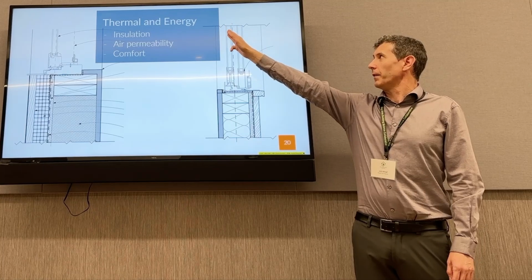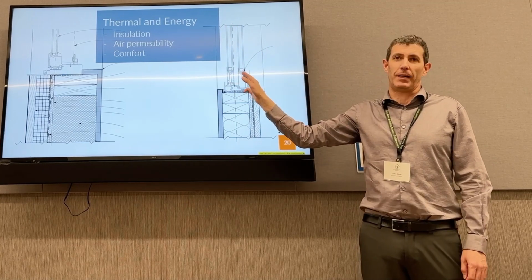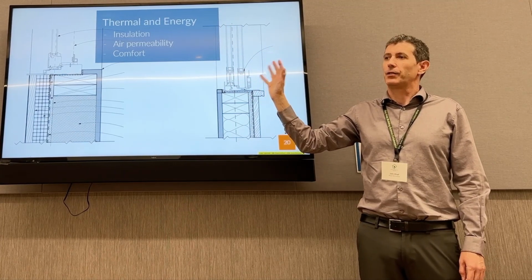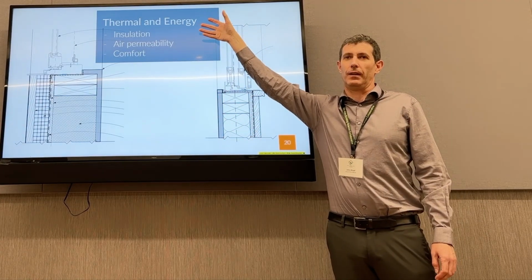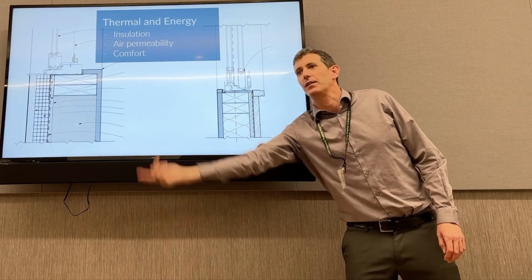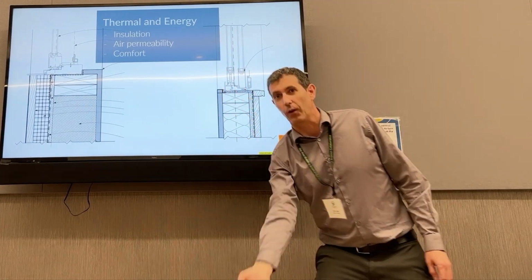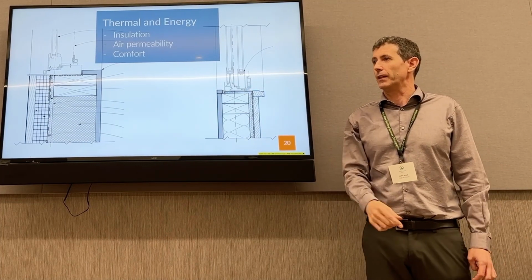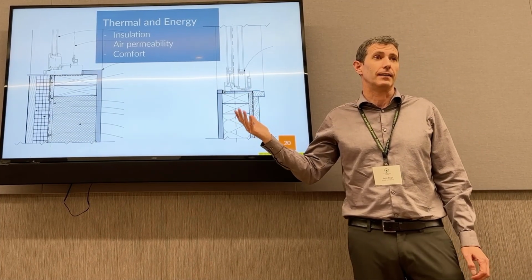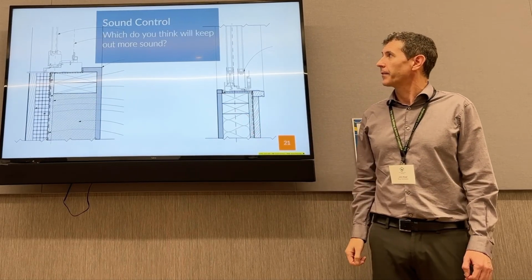In the original construction, of course, this would have been single pane glass, so we at least eliminated some of the coldness that creates that airflow where the air gets so cold that it sinks to the floor. And as it sinks to the floor, it pushes across the room and creates that draft, the feeling of a draft, right? Even if air is not leaking in the house. Next slide, please.